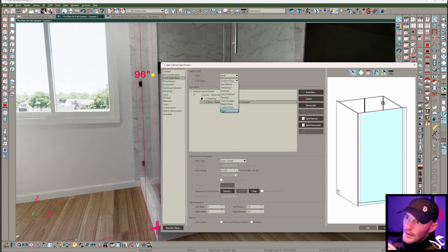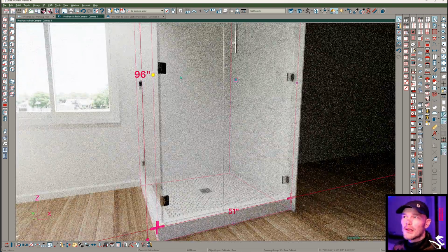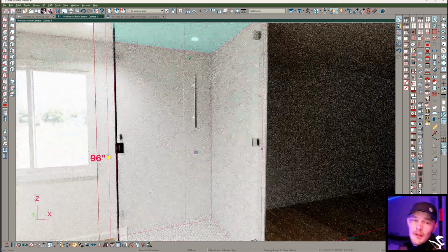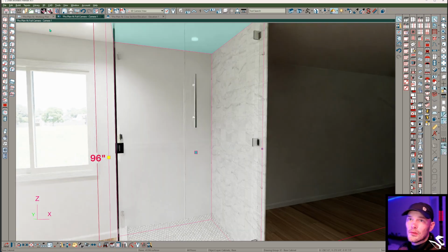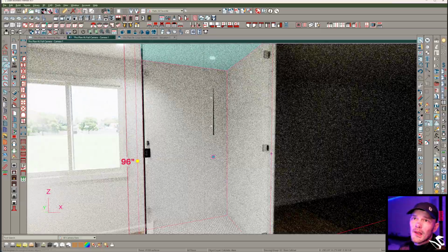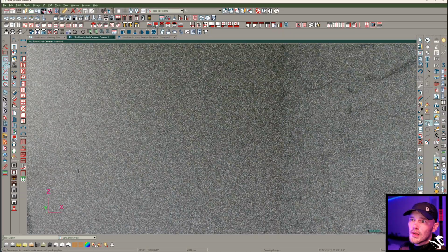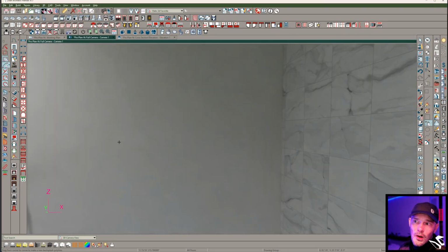All right, so instead of custom face, I'm just going to say none. Because this cabinet is drawn all the way to the ceiling, I can't just use the backsplash tool and apply it in this view, okay? I can't just come in here, use backsplash tool, and try to draw this out. It won't even draw. Why? Because this is a cabinet, it's limiting our ability to draw behind that cabinet as it's touching the wall.